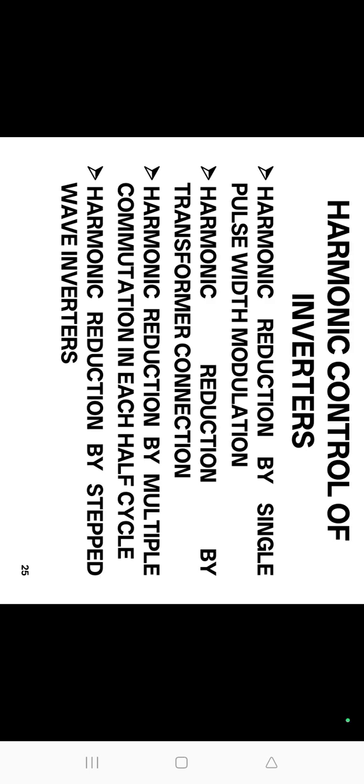malfunctioning can result. On critical loads, torque pulsations produced by the harmonic current will be harmful. Harmonic currents cause losses in the AC and DC systems and can even sometimes produce resonance in the system. Under resonance conditions, metering and instrumentation may also be affected because of distortion, etc. This effect can be minimized by reducing the harmonic content.